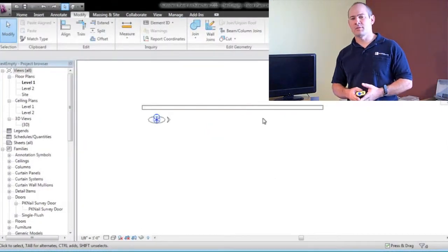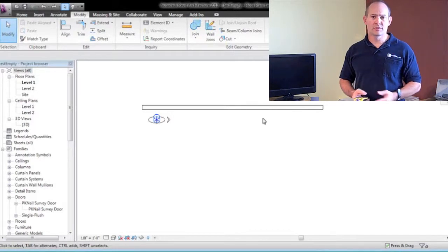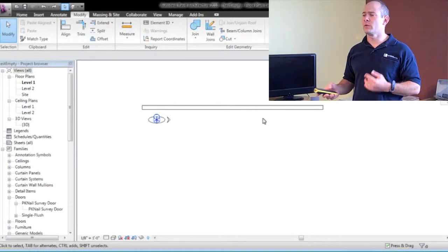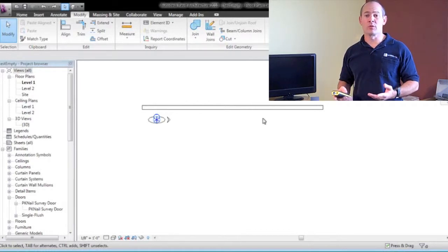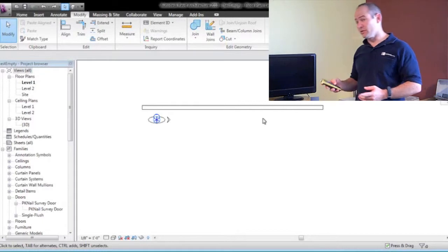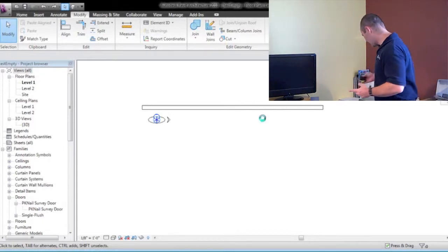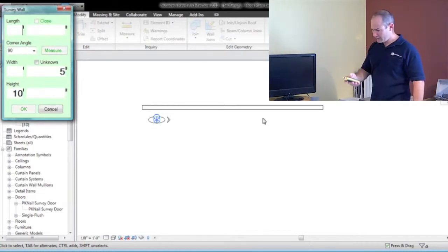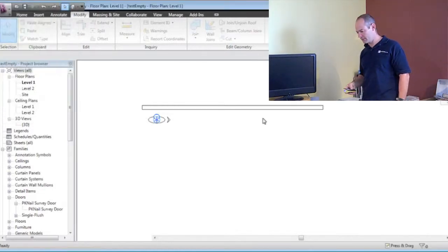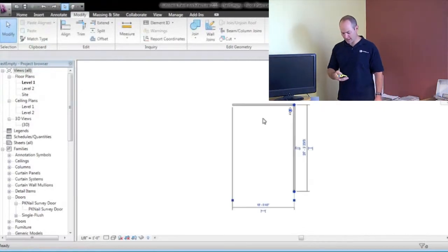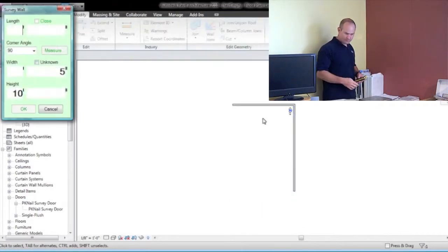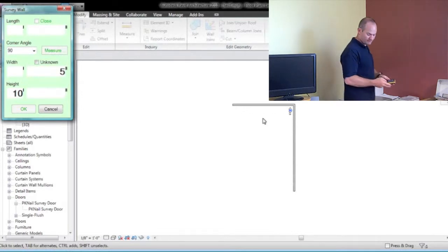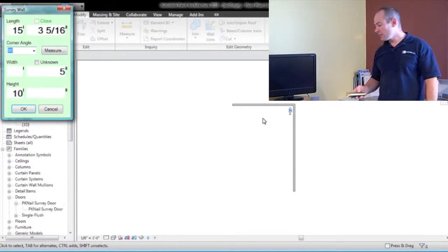The second way we can capture an angled wall using our software is through the closed room function. We can do this when we have three walls that are built 90 degrees from each other, or orthogonally. The first thing I need to do is build the second wall. So I bring up the dialog box, go ahead, measure, input, build it, add the next wall, input that, measure,